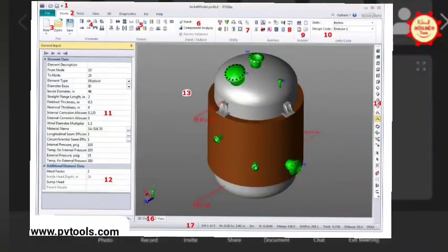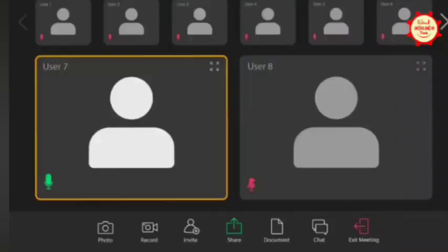While designing the inner shell, it will consider the external pressure as the full vacuum of the shell, and also the jacket higher pressure, whatever design pressure. It adds and automatically calculates for external pressure. Yeah, both addition. Got it. Thank you.